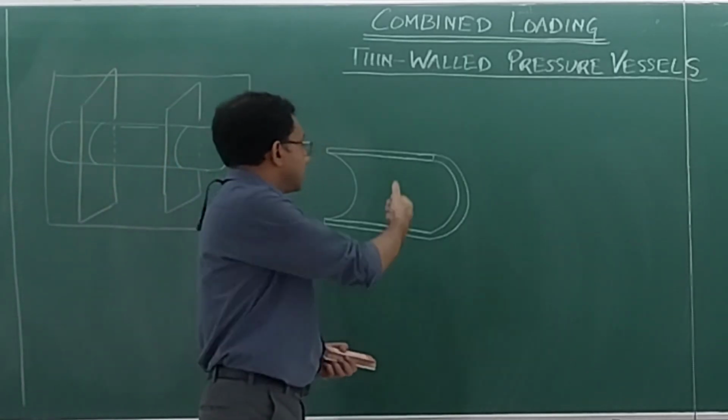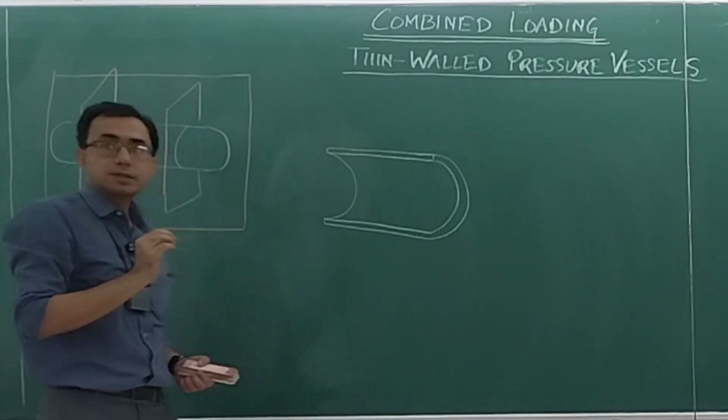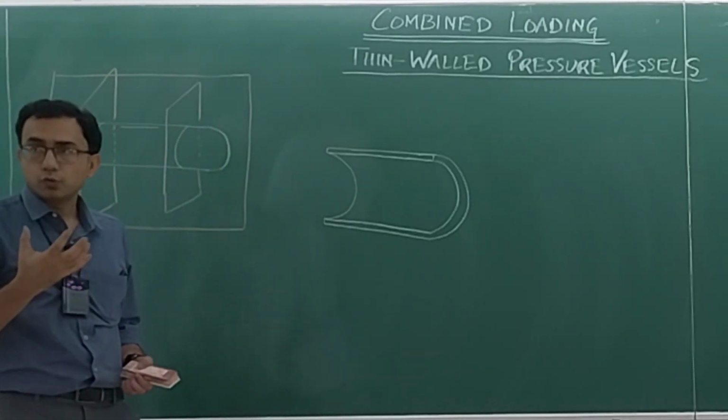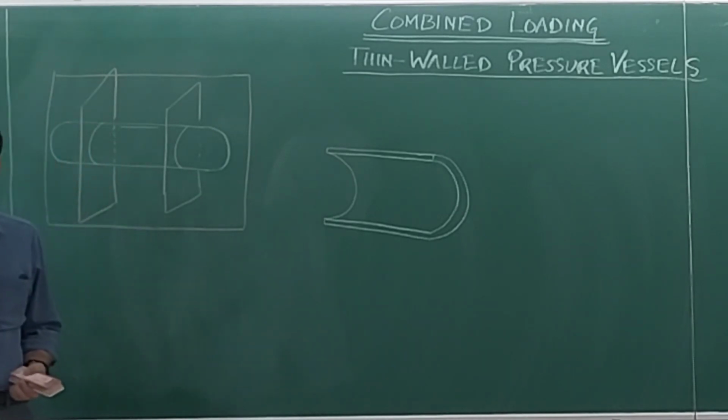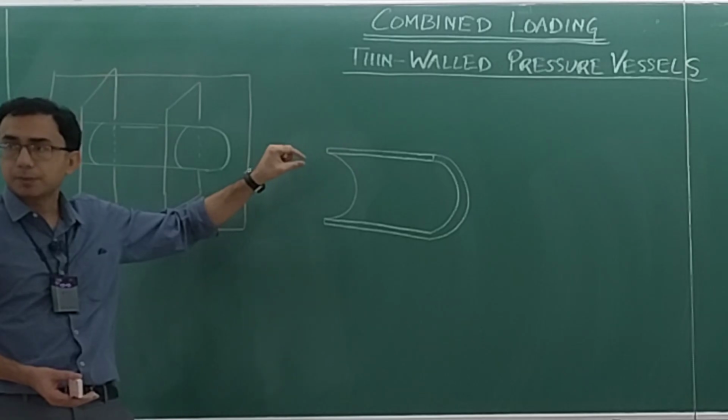Now, in this thin wall, you are going to experience the stress. Just imagine what happens in a balloon. When you blow into the balloon, the membrane gets stretched. Okay, and there is a stress developed in that, and if it exceeds a certain amount, it bursts. Okay, in a similar fashion, imagine that this thin wall is like the membrane of the pressure vessel.